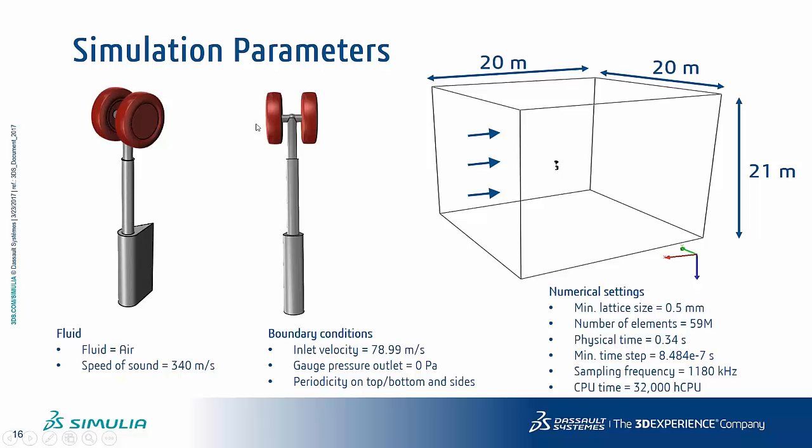So very simple, but still, despite the apparent simplicity of the geometry, it's not that easy, and acoustics is very complex in this region, and codes really struggle to get that right. So for this case, it's been tested, I think, in 2 wind tunnels, which are the F2 and the CEPRA 19, which are respectively for aerodynamics and aeroacoustics.